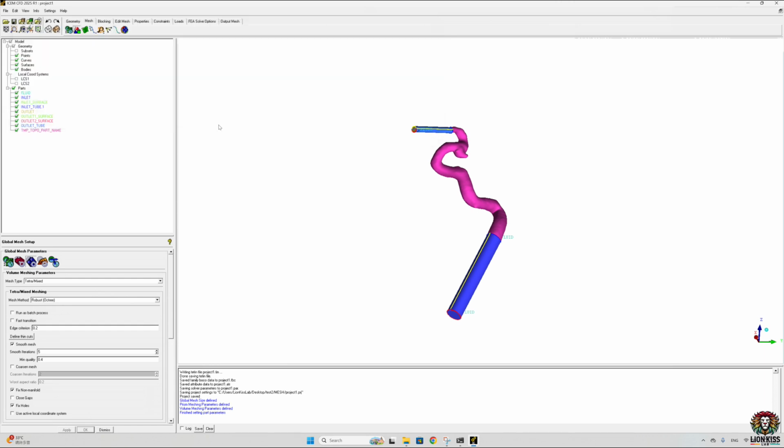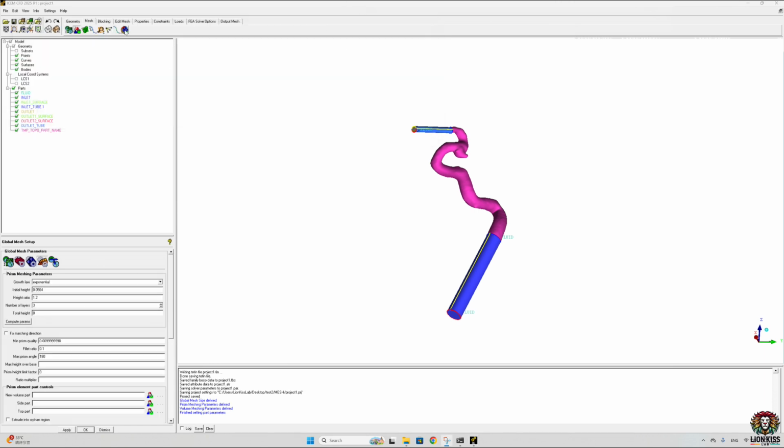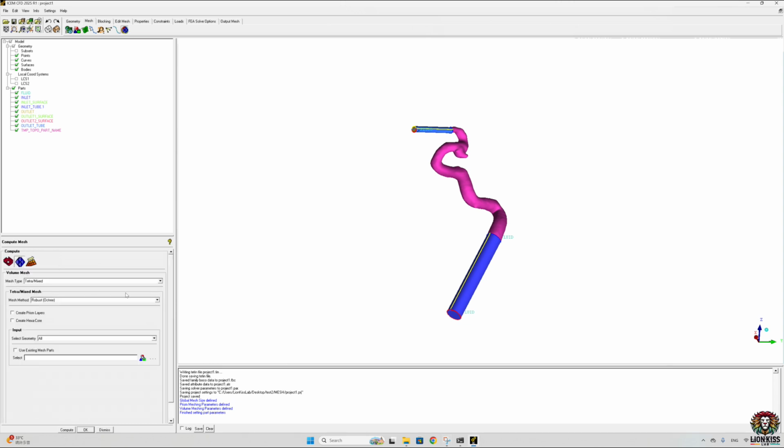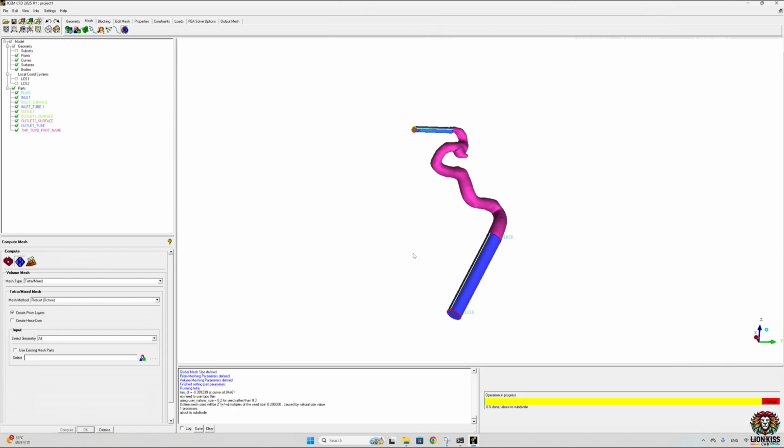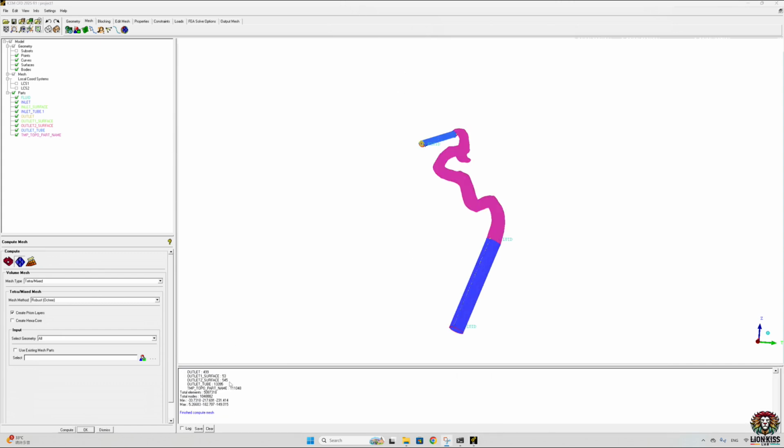Apply and dismiss. Now it's time to run our simulation. So confirm the transformation robust, and we need to click create mesh. Now the compute takes time, depending on the mesh size. So now the compute is finished because I just skipped the mesh timing.